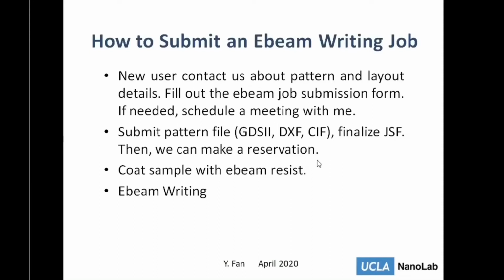So after that, we can make a reservation. Before you schedule time, you need to code yourself who is the resist. I can help you if you cannot access the clean room, but if you can access it, it's definitely better that you do that by yourself. Later is e-beam writing. After that, the develop work is also the same. You can develop it by yourself if you are a user here, or we can develop for you.